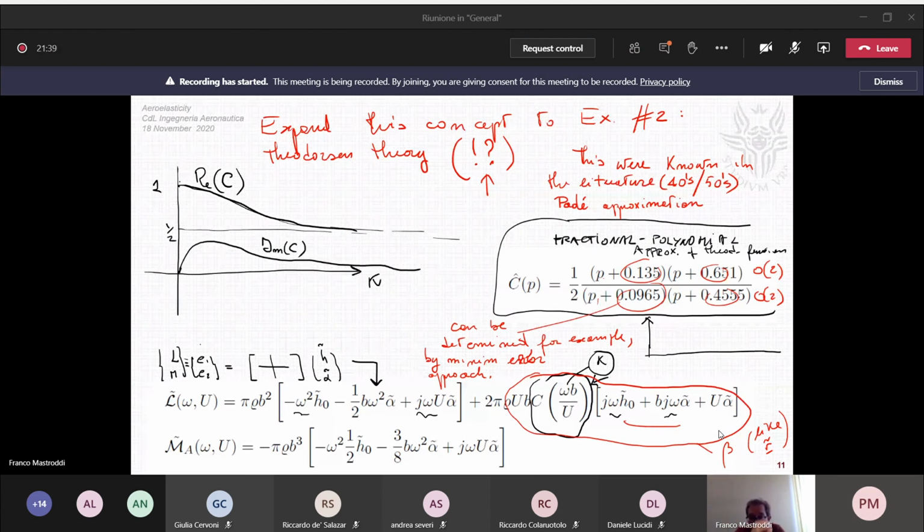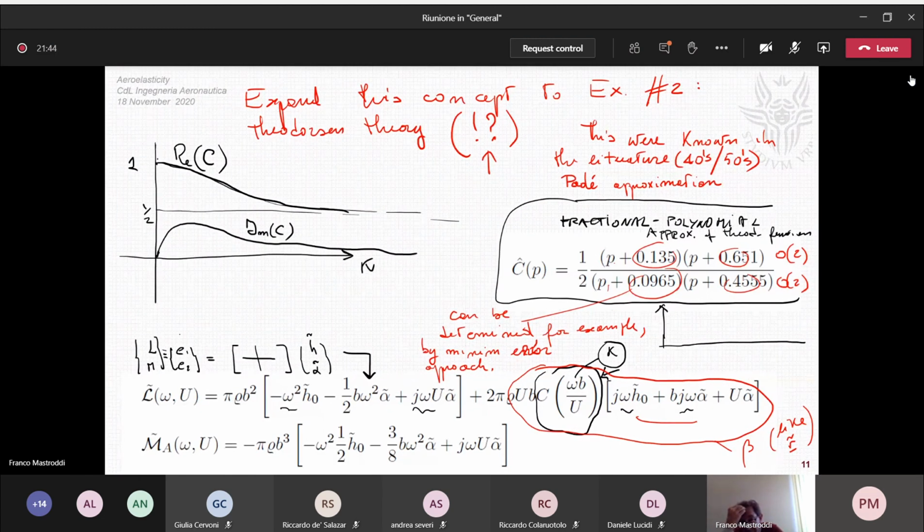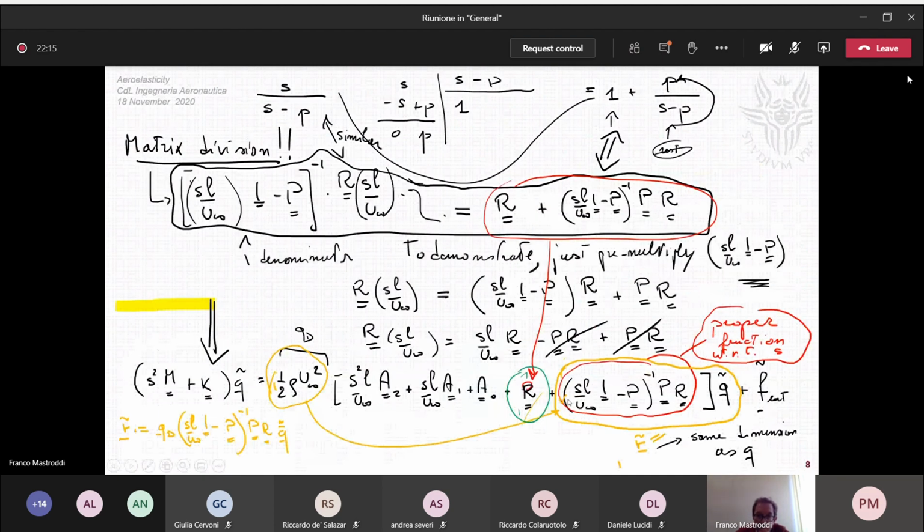This is what we found, and we also made this morning a final connection between this approach and a similar approach that can be performed for the 2D airfoil analytic theory by Theodorsen. This technique allows us to approximate the Theodorsen function C by using a fractional form, exactly like in the way we did for the rotational part of our operator. Note that the analytic theory of Theodorsen gives a very similar structure to the interpolating function we assumed.